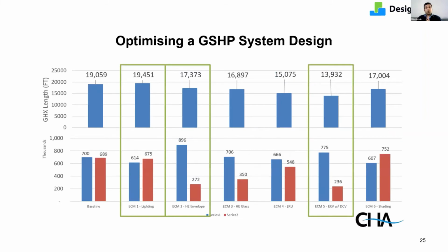So optimization was used to identify the combination of energy conservation measures that had the greatest combined impact, and not just the energy conservation measures with the biggest individual potential without considering the whole picture. And the result was Brendan was able to reduce the ground heat exchanger length by about 1/3, which offset the cost of other energy conservation measures to further improve the design. This is an excellent example that really demonstrated the impact of intelligently combining key design variables for maximum impact.